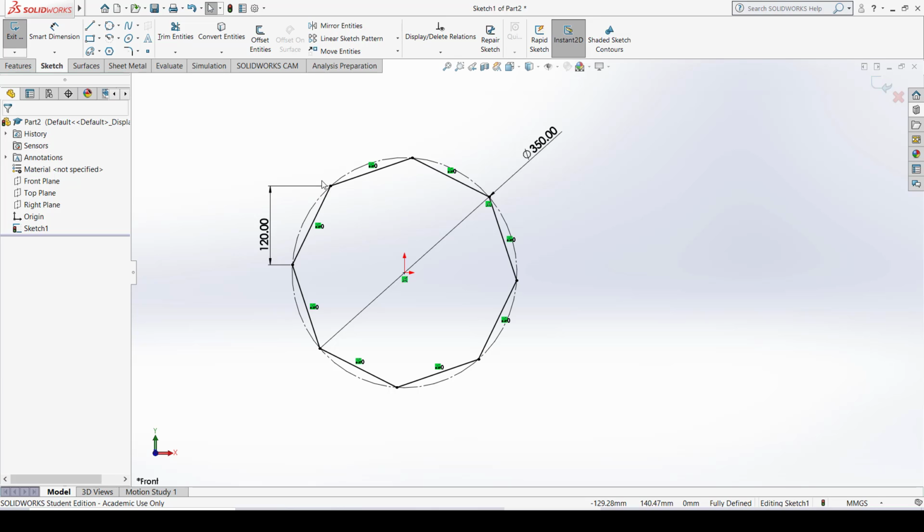If any line or point is blue in color, it is movable. You can move it, you can edit it. So when we transfer 2D to 3D, there may be a chance that that element will not get converted into 3D. It may distort your drawing and produce some error while converting 2D to 3D. So make sure that your drawing is fully defined. For fully defined structures, we prepare a lecture on it, and I will show you how to make your drawings fully constrained with the help of 3 constraint methods. That will be a later part.